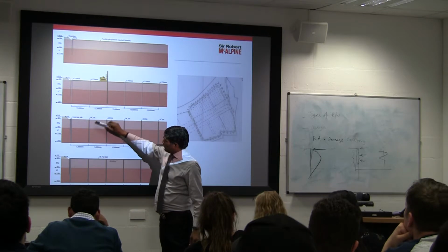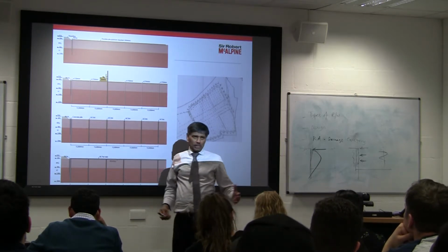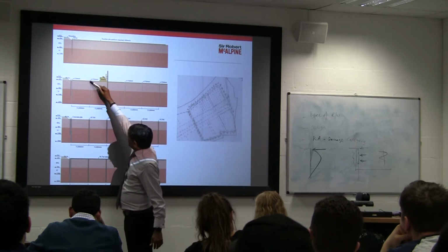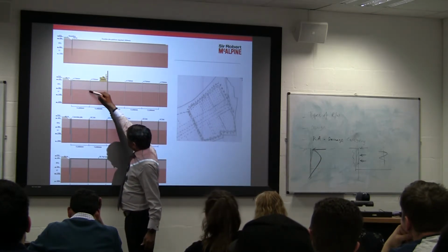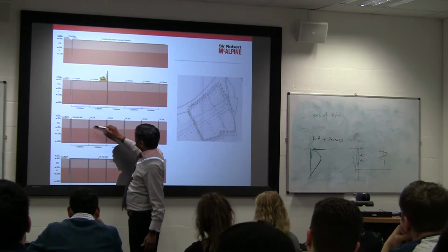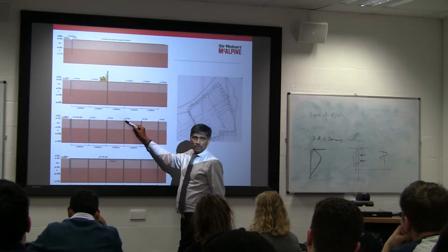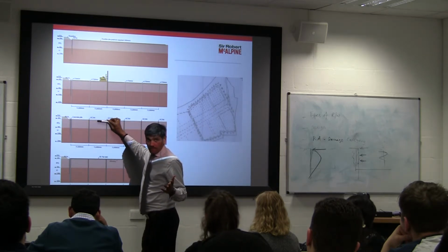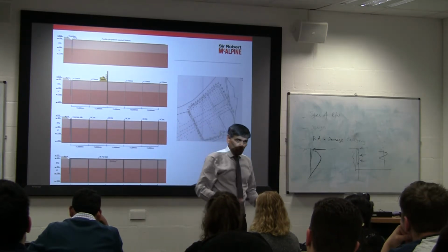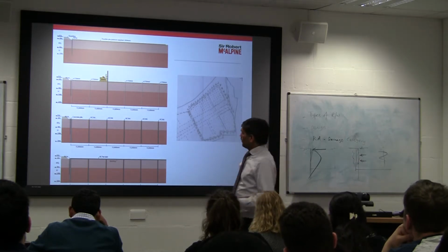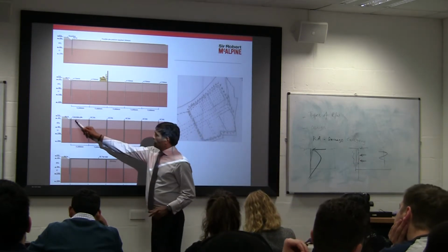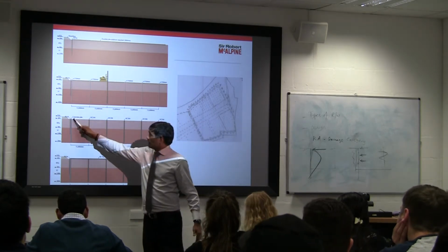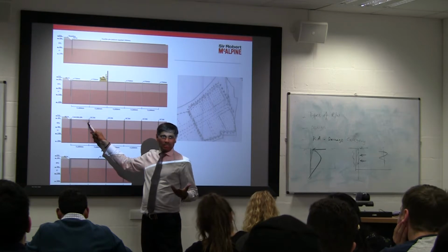And then we put what is called plunge columns, as I was saying. So you've got a bore, your piling is done from here, concreting is done to that point, and then you drop a steel beam or a steel column, UCs, and that is your plunge column. Once you've got that, you still have not dug here. Yeah? The piling rig is still moving on the ground, doing simply the piling and plunge columns. And what we are doing then is, on the ground, using that as a bottom support, we pour concrete straight on this. You see the advantage?